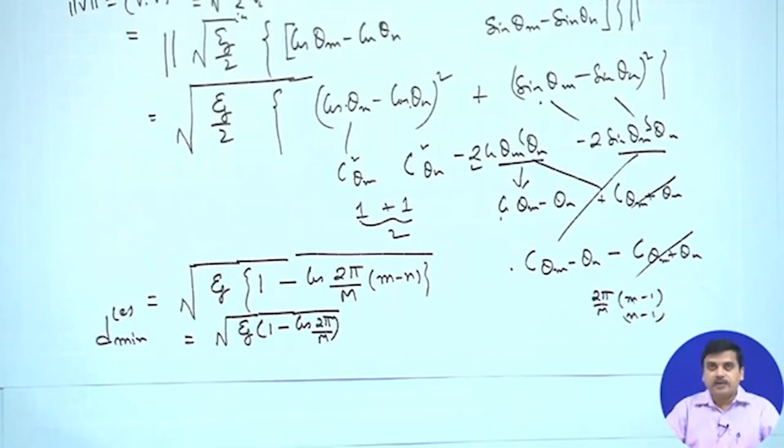So, till this point we have covered two important modulation techniques. One is the pulse amplitude modulation, where you are selecting an amplitude based on the bit sequence. The number of bits you would group together to select an amplitude would depend upon the number of amplitude levels. In phase shift keying, you are choosing the phase based on the incoming bit sequence.